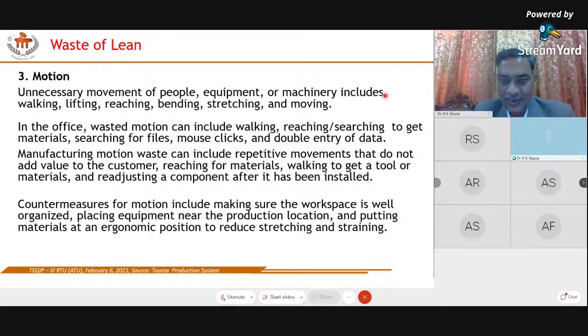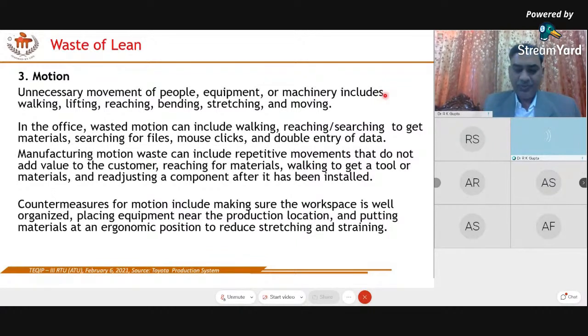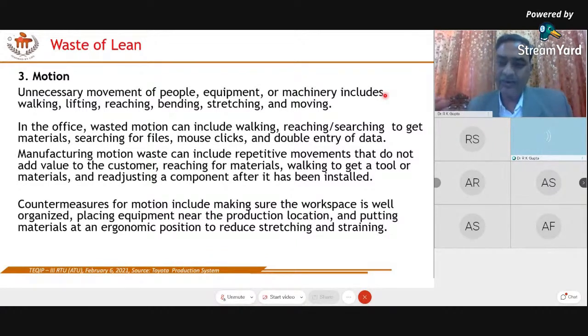So how to do it? We can do it by keeping the bolt in the left hand and picking the nut from the bin, or before picking the nut from the bin, we pick the washer from the bin, put it over the bolt, and then drive the nut, and this is the complete assembly. What improvement can be done in this case? In this case, the left hand is idle and the right hand is moving. The movement of this right hand takes time.